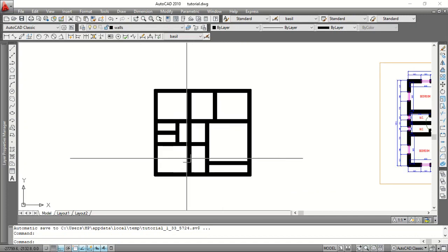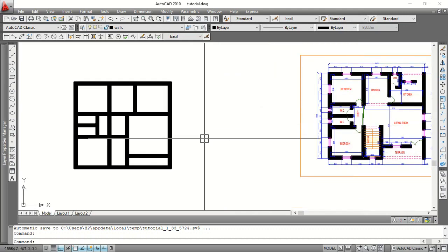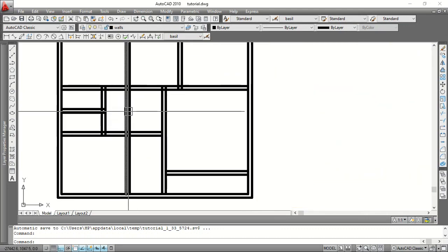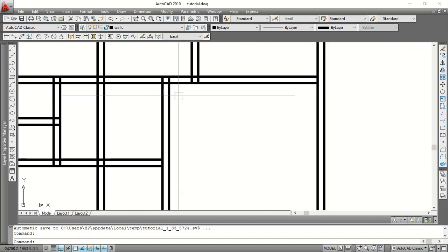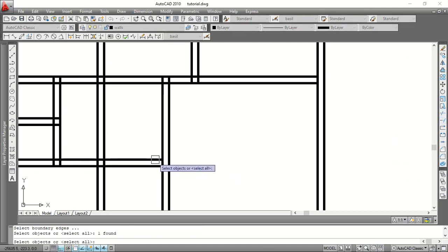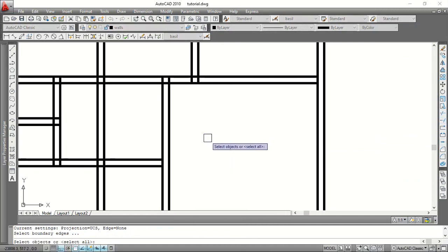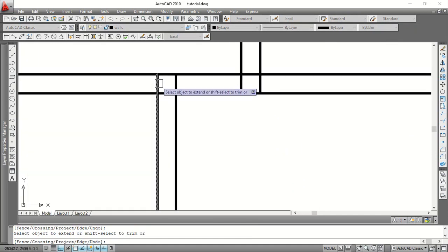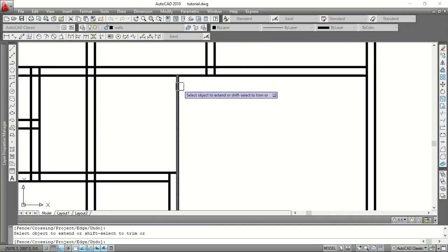So I've succeeded in almost bringing out everything. You could see the staircase is automatically out because it's the same wall. Okay, so I haven't done this. You are not done with your drawings. This very wall is not supposed to go on to this point. So I picked my extension tool first so I could extend this. Right click, extend. Oh, sorry. Let's do that again. Extension, right click. Good. Then I don't need this, so you trim, you trim, you trim. Press down your shift key and you trim.